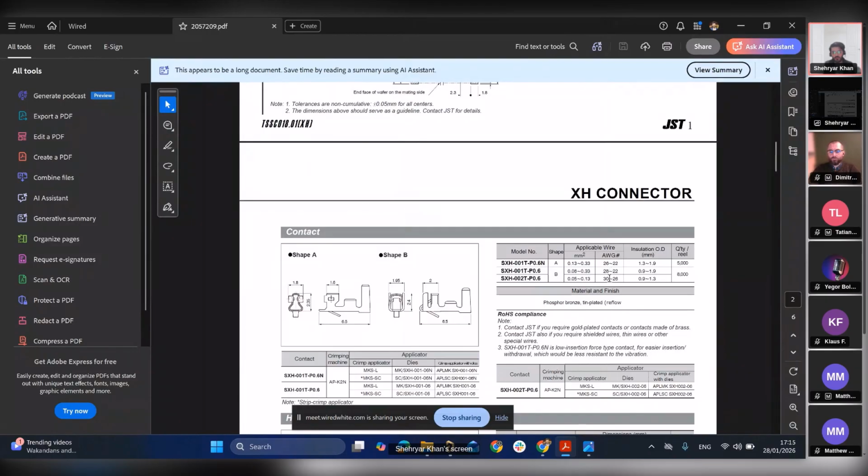So as your number increases, let's suppose from 10 to 11 to 12 to 13, your wire size will decrease. That's something about the American wire gauge system. So the higher the wire gauge number, the smaller the diameter of the cable or the wire.